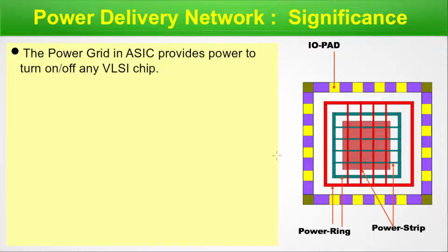Next, we have the IO pads here. We have IO filler. Here with the picture, you are getting familiar with the entire chip, how the things are there from a bird's eye view. Here is a corner cell and here is the core. This is where the silicon, we call it core.